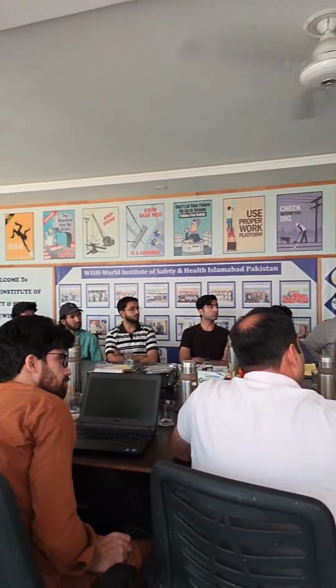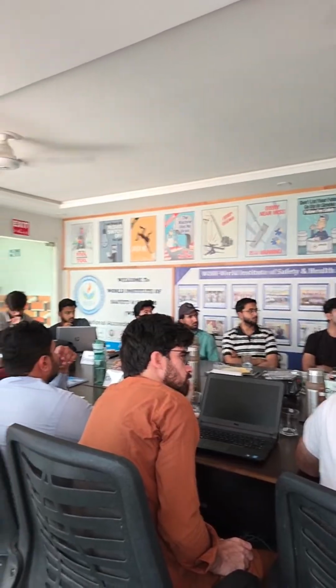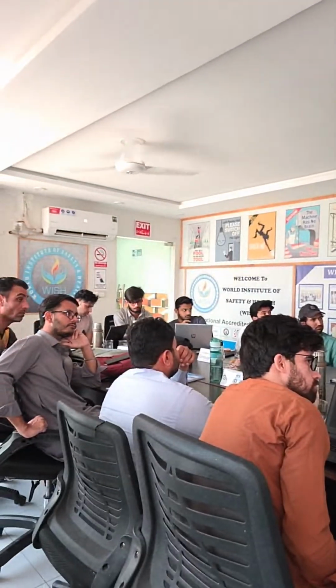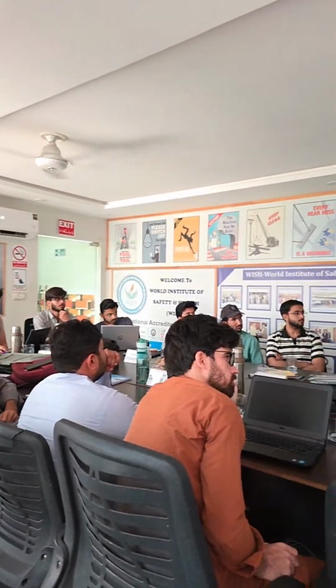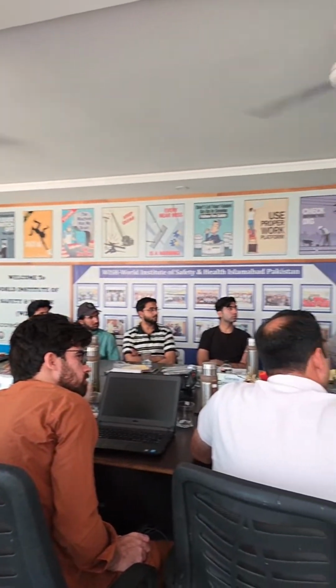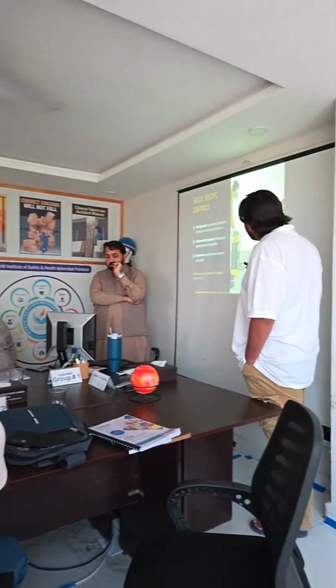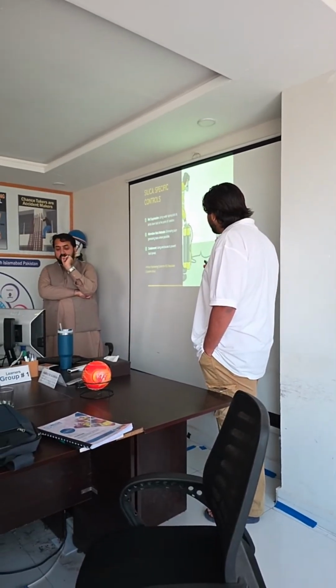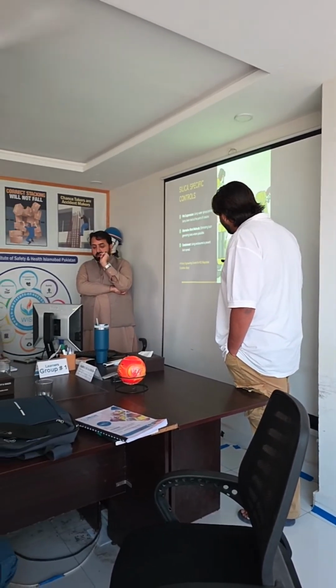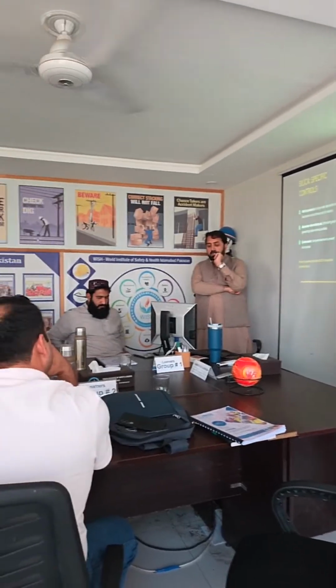Silica specific control: wet suppression using water spray. Wet suppression means water suppression, water spray. Using water spray to damp down dust at the point of creation. Alternate work method: eliminating dust generating tasks where possible. Good. Containment: using enclosures to prevent dust spread.